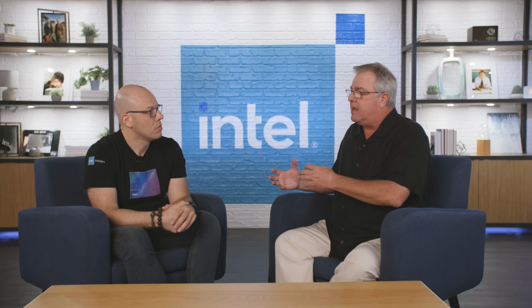And what about the XMX extensions we were talking about earlier? Oh, so XMX is this whole matrix thing. And on graphics, the matrix extensions are harder to make use of. They're mostly about accelerating AI-style processing. So XMX on graphics would typically be doing a post-process like XeSS. XeSS is obviously enhanced for Xe2, and it uses our XMX instructions to get great quality super sampling. And that now applies to our integrated products as well.